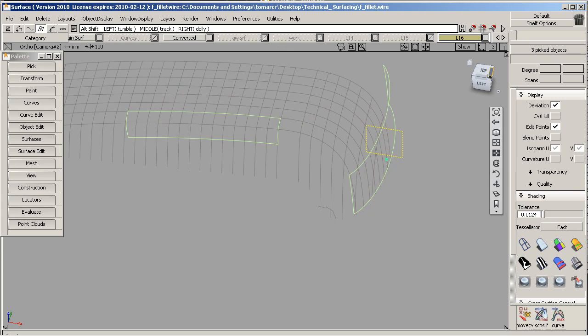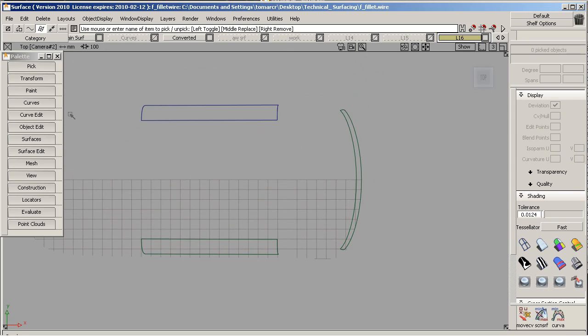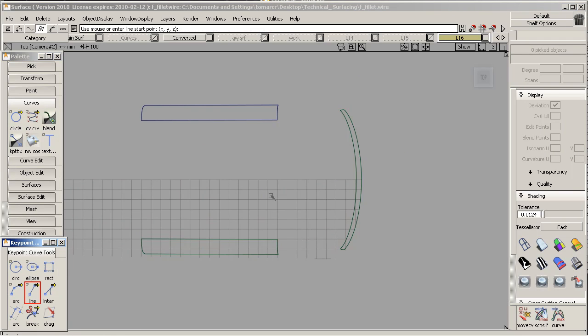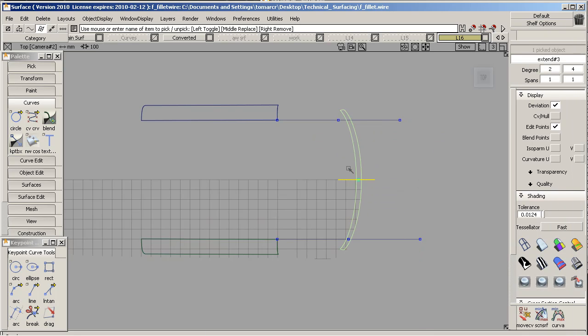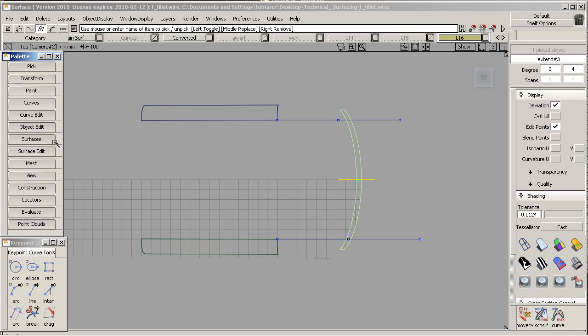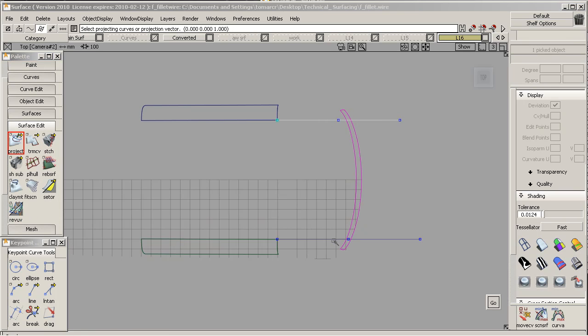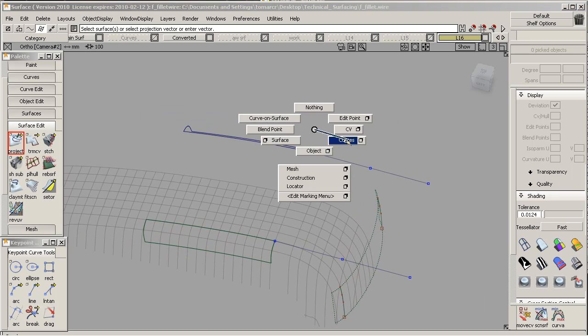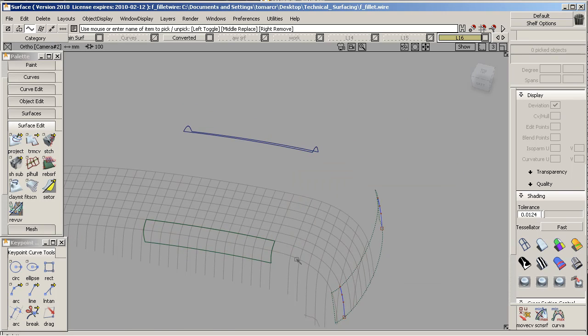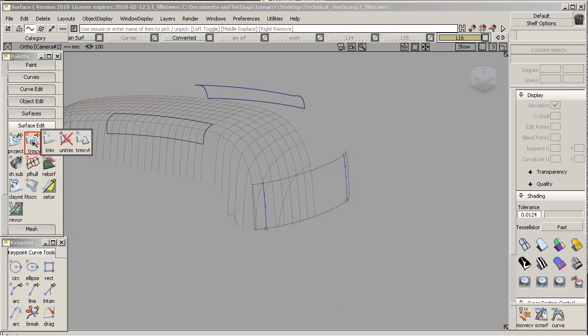We're going to go into top view, and we're going to put some curves on there. Okay. Now this is a reason why I didn't touch the back surface and I didn't make it to scale, because we're going to project this and then trim for that surface. So we're going to project the 2 curves. Okay. We pick the curves as we don't need them. And we're going to trim convert this surface. Okay.